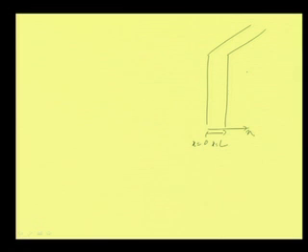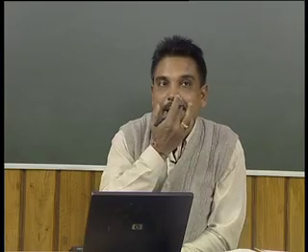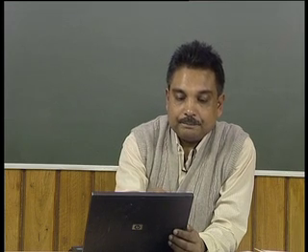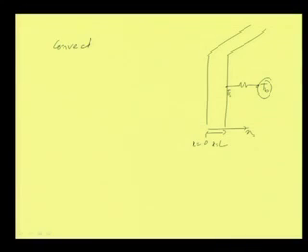Initially we thought of this as a surface temperature that is a constant temperature of the surface. But actually, if we see that there is a bulk here, then the bulk temperature can be constant, and there is a resistance between the surface and the bulk. This is the surface temperature T s, and there is a bulk temperature. So the bulk temperature, or the temperature of the external world, is fixed, whereas the temperature of the surface may not be fixed. But the heat transfer coefficient could be assumed to be constant. That means the whole body is placed in a convective environment.